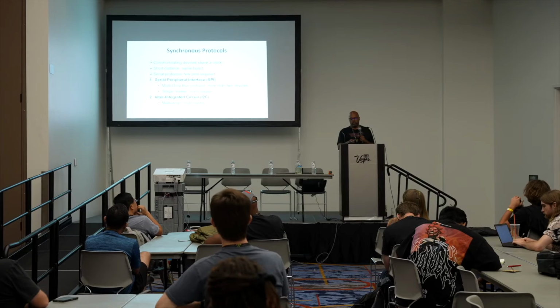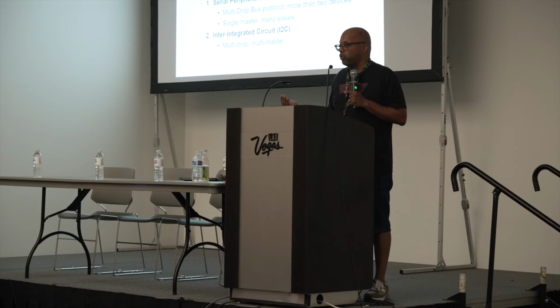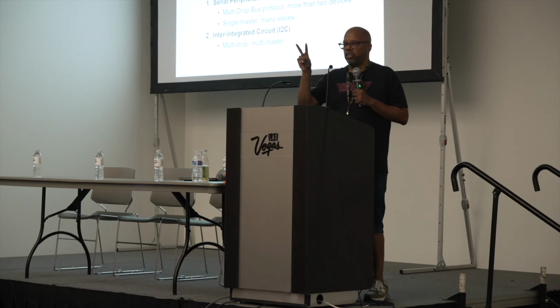Another thing is synchronous protocols. I'm going to have to whiz through this, but when you have like a board and you want to connect it to another hardware device, you have to use some kind of communication protocol. Synchronous protocols are common. They're faster. They share a clock. Anyway, I can't go into details of the protocols, but SPI and I2C are the top ones that people use.